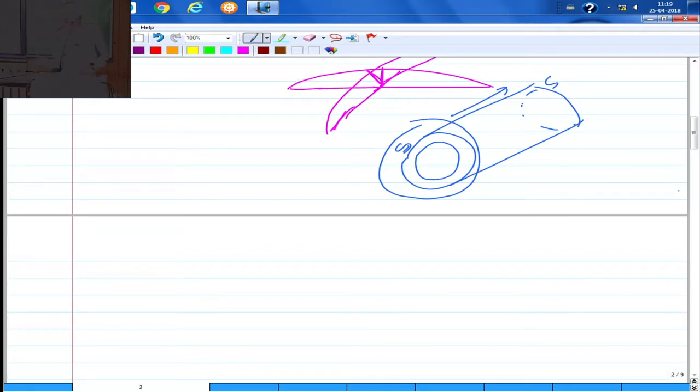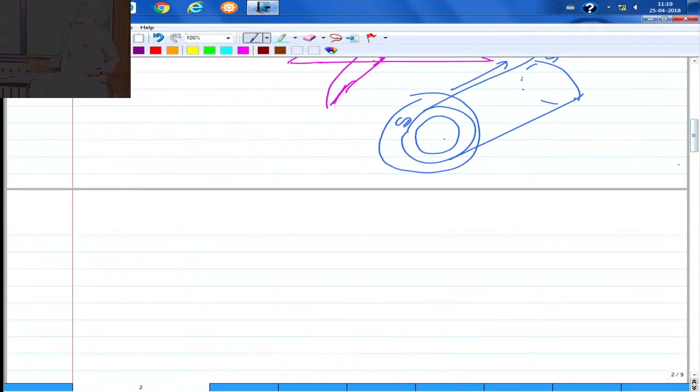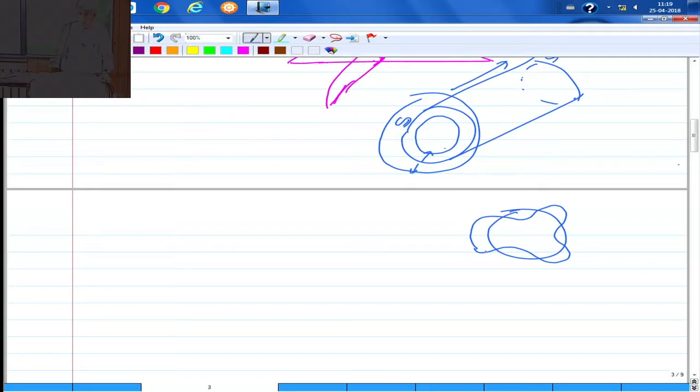Now the other possibility of deformation: when you look at one cross section, either the whole cross section is moving in or moving out, known as the axisymmetric mode of vibration. There is another possibility that if I look at one particular cross section, the modes can have shapes like this, something like this.